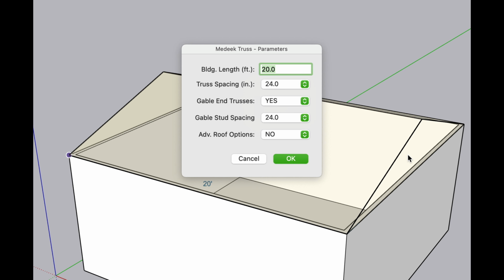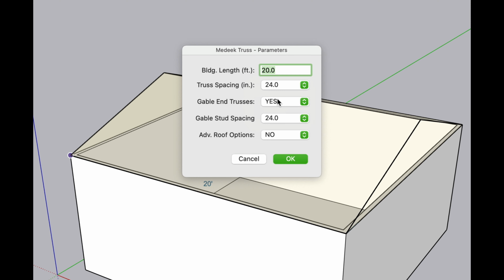So typically, if you're doing like an open porch cover or something, just stick with the Fink trusses, because that way you won't need a beam across there to support it. Now, you would have a beam here, obviously, to support the loads on each end of the span. Okay. But since we have walls here, we'll go ahead and put those in. And basically, it's just easier to attach material to those because it has straight slats, you'll see.